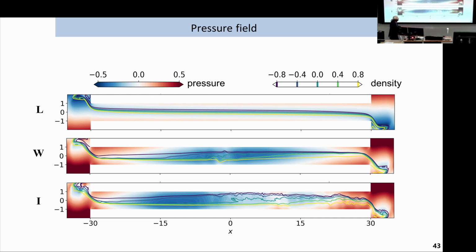So what you're actually doing is trying to push fluid down this duct too fast from both directions, and it goes, oh, in the middle I can't cope with this. So it goes for an internal hydraulic dump in the middle, and everything slows down as it exits the other end. And it's even more pronounced in the intermittent case, where the minimum is larger and extends more. And you can see that when it does go turbulent, things change again. So it's quite different dynamics, and we can't see that in the experiments. They can't measure pressure, not with that resolution. So this is very interesting insights.